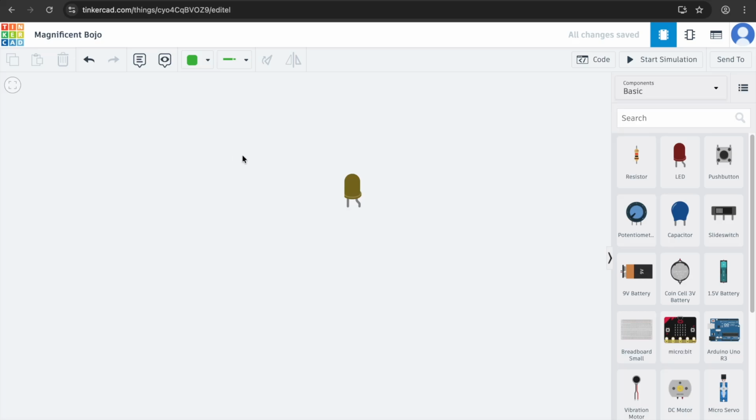A rule of thumb for most components that are polarized, like this LED, which means that they have a positive and a negative, is that they will usually have a longer positive leg, or anode, than their negative one, or cathode. Here you can see the bent one is positive, while the straight one is negative, as the bent one is slightly longer. However, in real life, it'll be much easier to tell that it's longer.